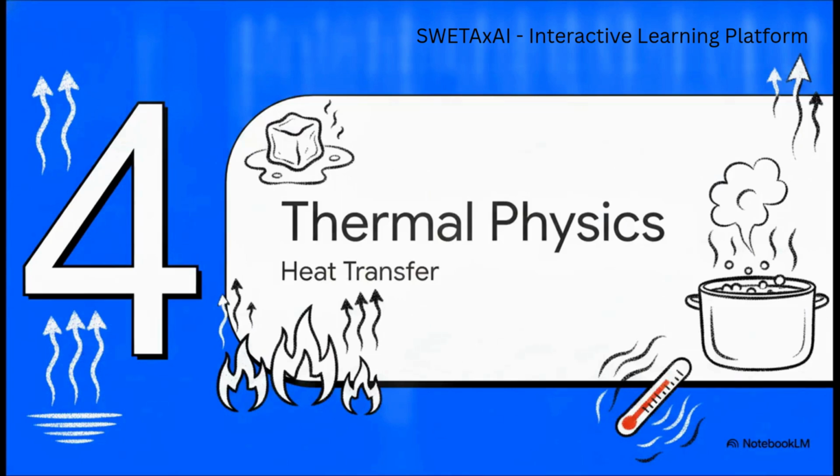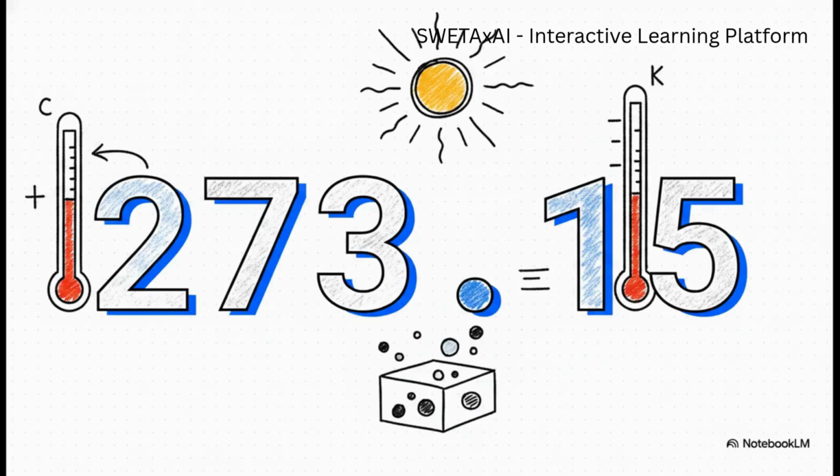Let's keep moving. Section 4, thermal physics and heat transfer. Before you do any single calculation here, burn this number into your brain. 273.15. To safely use thermal equations, you absolutely have got to remember to add 273.15 to convert your Celsius temperatures into Kelvin. Forgetting that step is literally the easiest way to throw away marks.